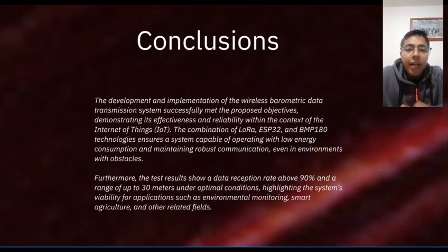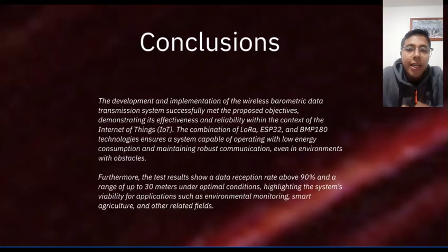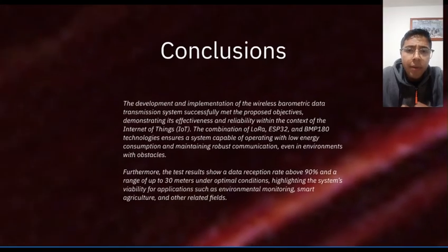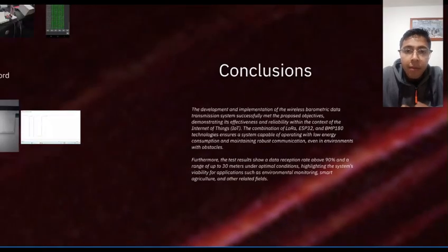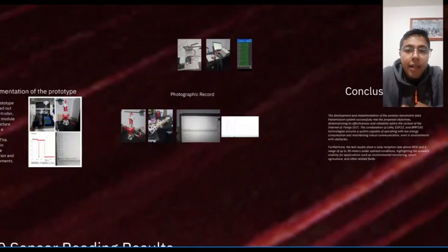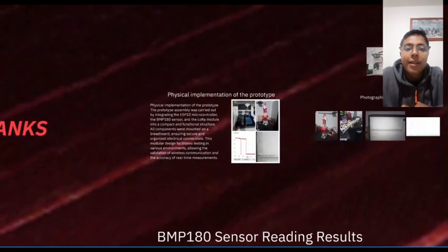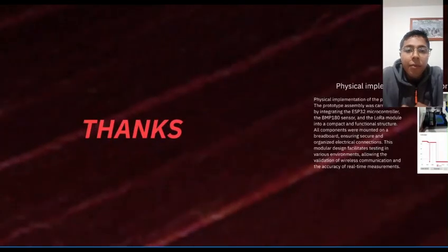To ensure electrical compatibility, essential attention was paid to logic level signals. The ESP32 operates at 3.3 volts. Logic level shifting circuitry was required to protect the device from potential overvoltage.